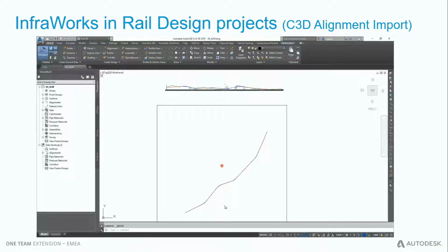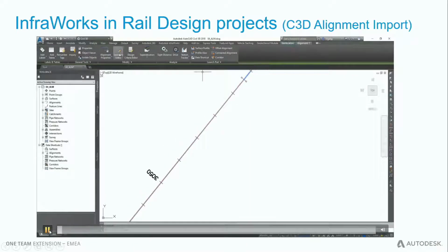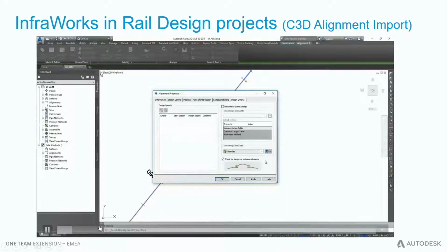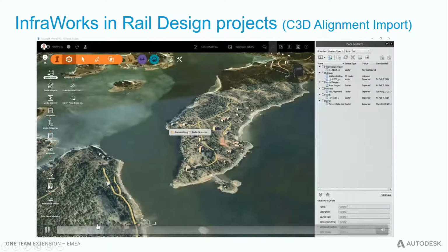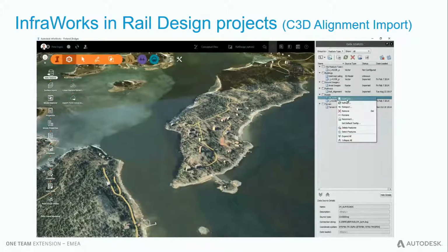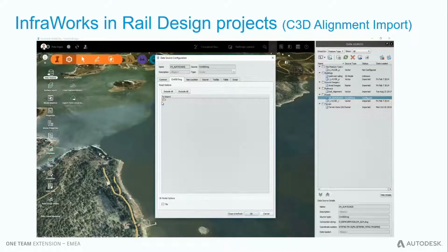So what I mean here is basically a road alignment, right, which we've designed as a rail track, and then we save it. I'm just here saving it. Let me just save on time. We import, or we actually link to the Civil 3D model inside of InfraWorks. Depending on the different objects within the civil model, it will take time to read it all. Once it's read, you will have the option to select, for example, the surface or the rail, the track or whatever. Here we're just selecting the track. And then also no need to drape it because it has 3D elevation.